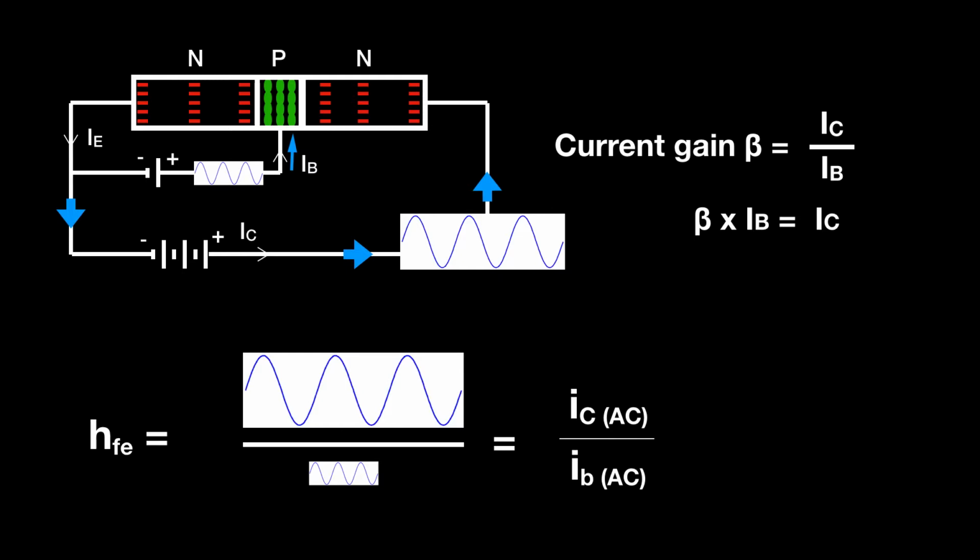Now we're going to see values for beta of perhaps 20 or 25 for a large power transistor. Its purpose is not particularly to give a lot of gain. Or you might see values of 3, 4, 500 for a small signal transistor whose purpose is to provide gain.